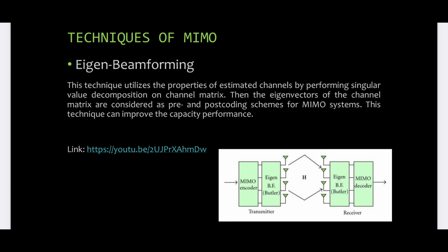Eigen beamforming is not limited to forming a simple beam in three-dimensional space. It is not adversely affected by scattering objects or multipath reflections, as an eigen beamformer receiving a signal in a non-line of sight or NLOS situation with multiple reflections may form an effective antenna pattern that increases gain in multiple directions corresponding to the individual reflections. Using digital signal processing, MIMO systems have the ability to adapt these patterns on a packet-by-packet basis.